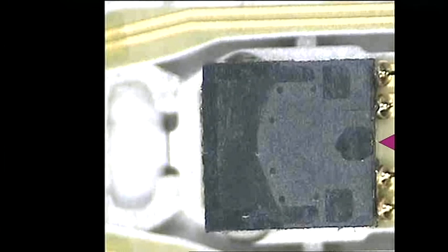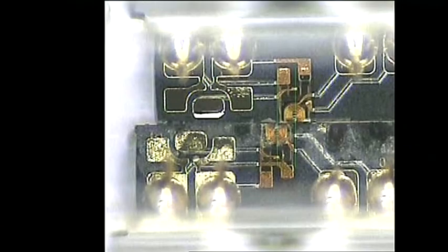Now, yes. I said something earlier about head alignment. For some hard drives, they completely don't care about how the heads are aligned, but others need a very precise alignment of the heads. Otherwise, they fall off servo when you switch heads.